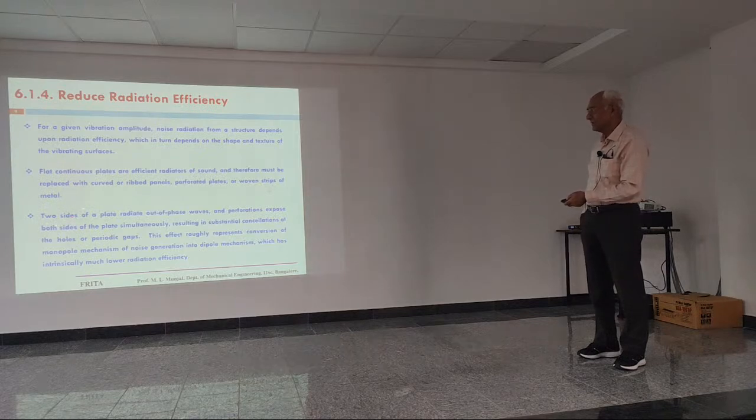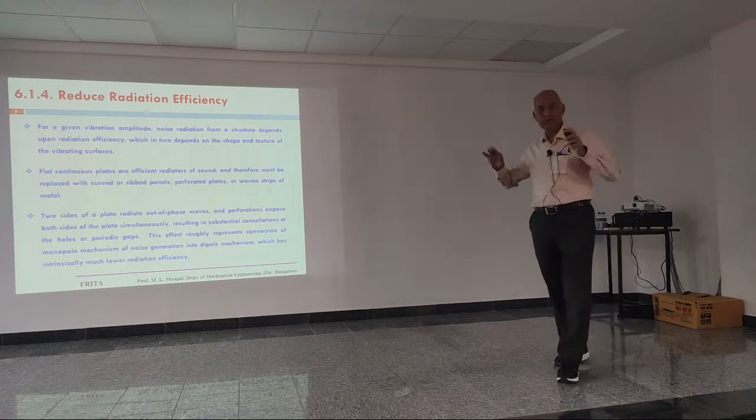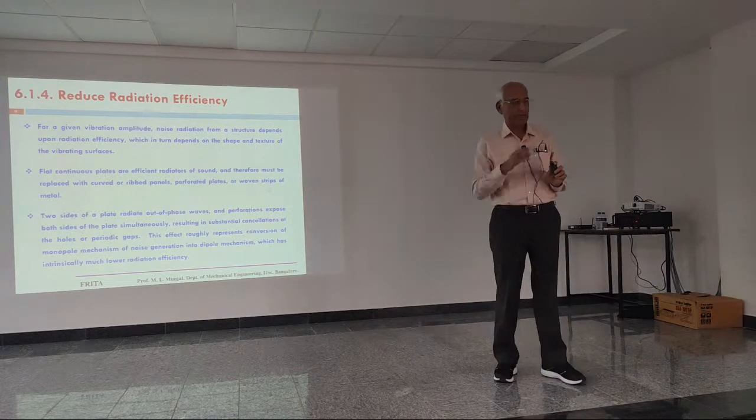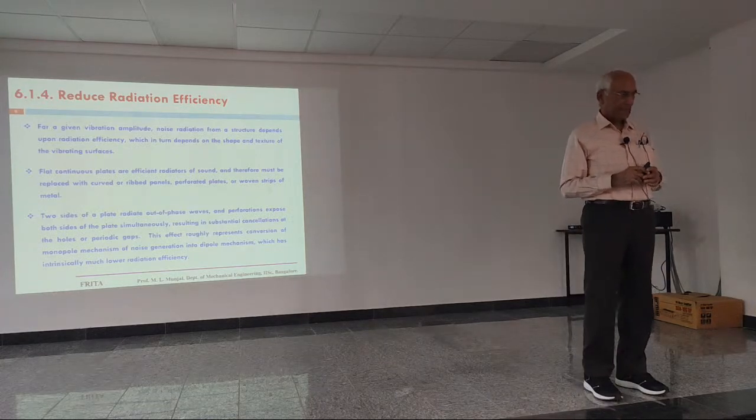The two sides of a plate radiate out-of-phase waves, and perforations expose both sides of the plate simultaneously, resulting in substantial cancellations at the holes or periodic gaps. This effect roughly represents conversion of the monopole mechanism of noise generation to the dipole mechanism, which has intrinsically much lower radiation efficiency. I am not going to talk about monopole, dipole, etc. But all I am trying to say is that